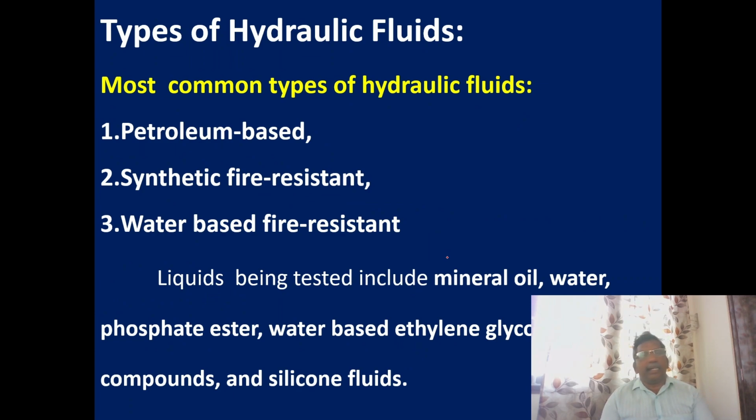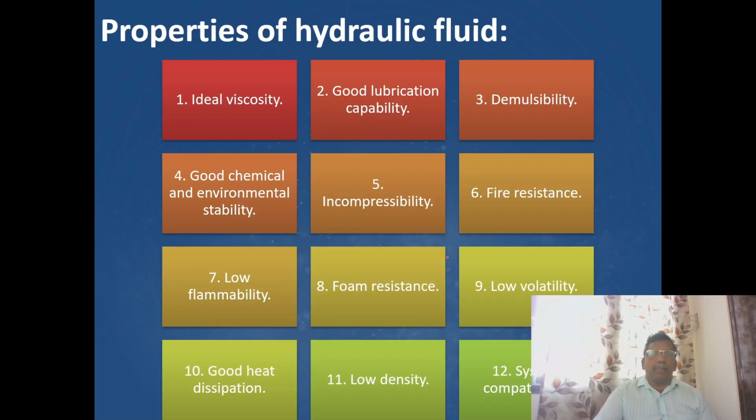Okay. Different types of fluids are used. Some of the fluids are petroleum based, fire resistant, water based. So nowadays we have fluids with mineral oil, water, phosphate ester, water based, ethylene glycol compounds, and silicone fluid. Now some new advanced fluids are also being developed to reduce the expenses in fluid.